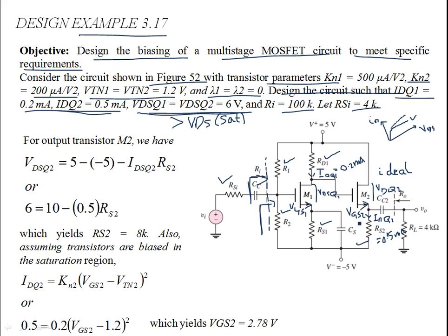That gives the IDQ1. Then from that current you find the resistance. That's how you determine the DC biasing. So for the design, you have the Q points, the currents and voltages, VDS and IDQs. So what are the resistances that ensure these voltages and currents? That's what we are after now.